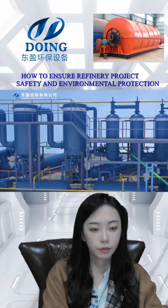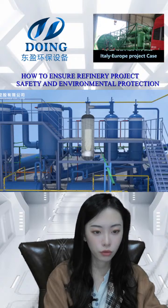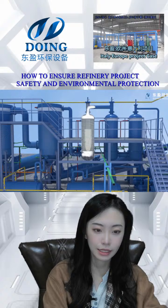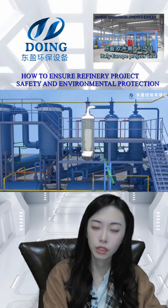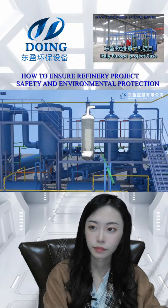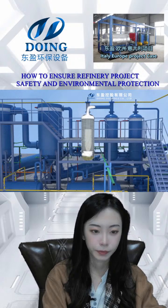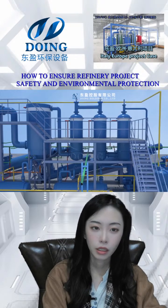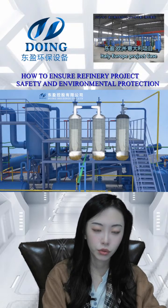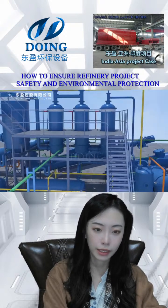And now we come to the vertical condensers. This is used to increase the cooling area and to ensure all the gas is condensed. You can see there are several tubes inside, 37 tubes. And we will go through the 3 water condensers to make sure all the gas will cool down and we can get the fuel oil.